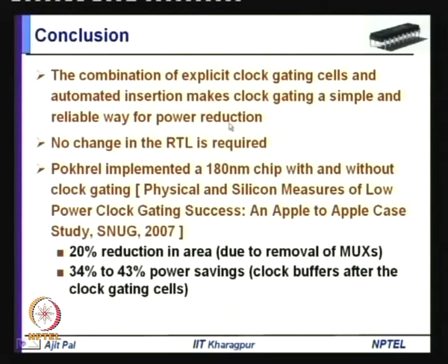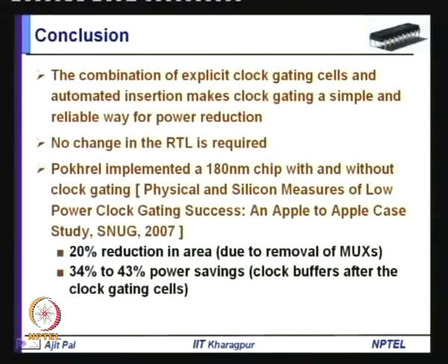But with the availability of suitable tools which will do the necessary analysis, later on I shall also discuss the CAD tool available for this kind of thing, and you will see that now it has become a very reliable way for power reduction. And there is no change in the RTL, that means RTL coding need not be changed, because you are not really changing any functionality. Since you are not changing any functionality, that RTL coding part remains unaffected.